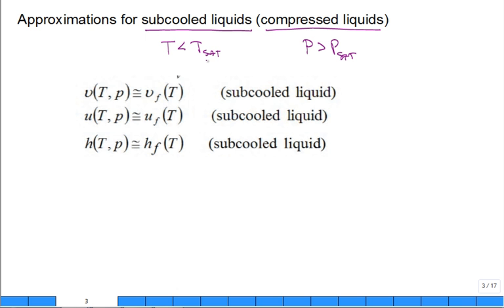Oh. And look, maybe go back again from the triple point to the critical point, thinking up here, this is all the liquid. And you can have a perspective from temperature or perspective from pressure, but you're above this line. That's where liquids exist. And then you can think about them being colder than the saturated liquid or higher pressure than the saturated liquid.